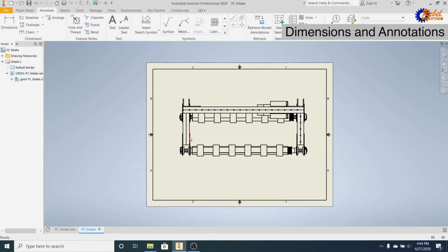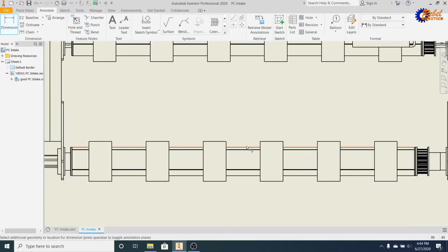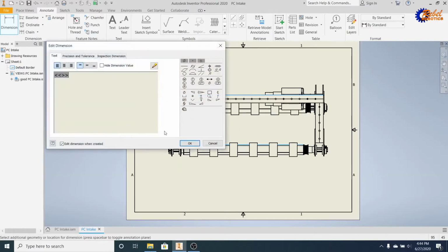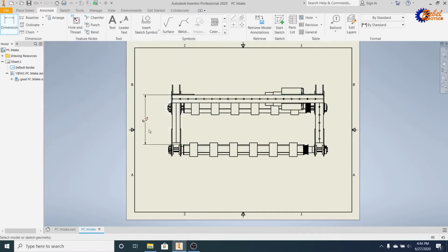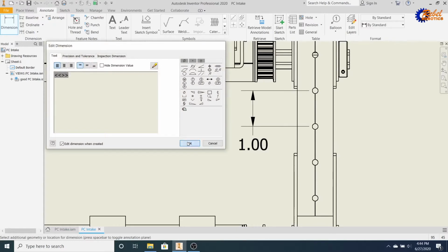The next step in making your drawing more useful for people to recreate your CAD work is to add dimensions or any other annotations. To create a dimension, go up here in the Annotate tab and click Dimension. Then, just create a dimension between any two lines or any other objects or points, and you'll get dimensions that it'll read out to you and can be seen on the paper when printed. Here, you can create any dimensions between pretty much any point. Let's say like 2 points right here. Here, and so on and so forth.